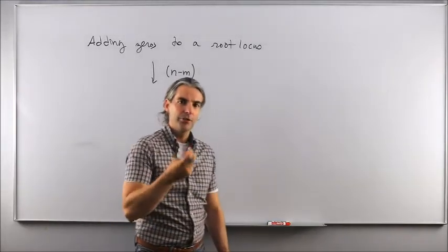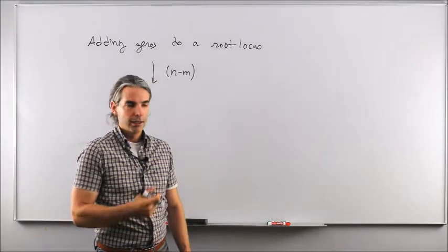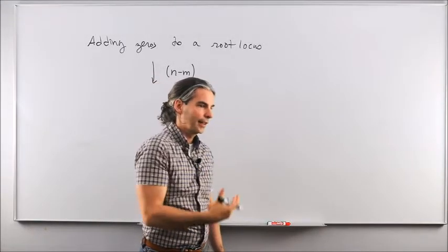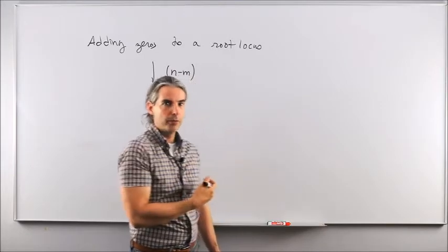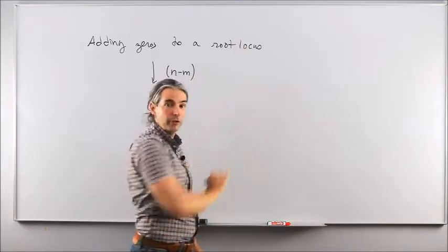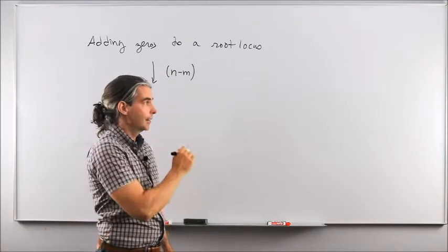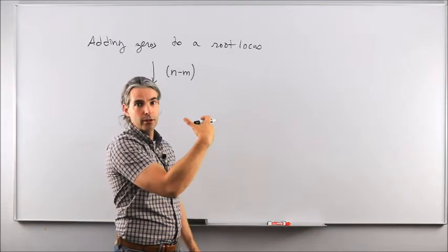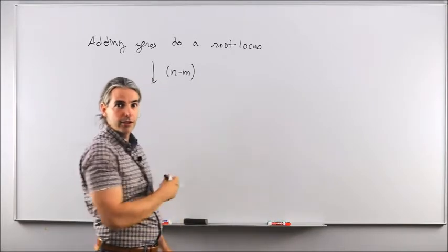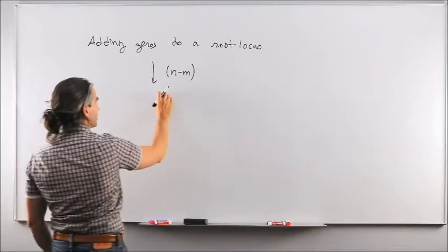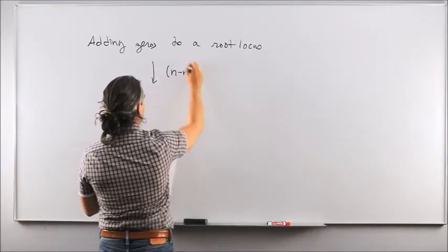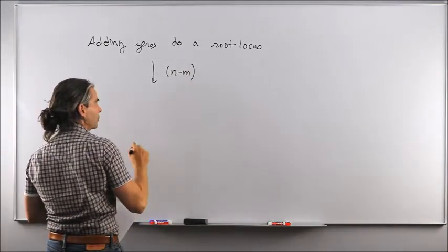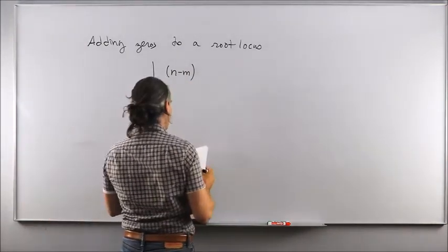Well, that makes sense, because if you add an extra 0 to the root locus, that 0 will be able to act as a receptacle for one of the poles that would otherwise fly off to infinity along an asymptote. Now that pole that was originally flying off is being caught by this additional 0. Okay? So that is a great thing. So lower the number of asymptotes, or in other words, catching a pole that would otherwise fly off to infinity along an asymptote.